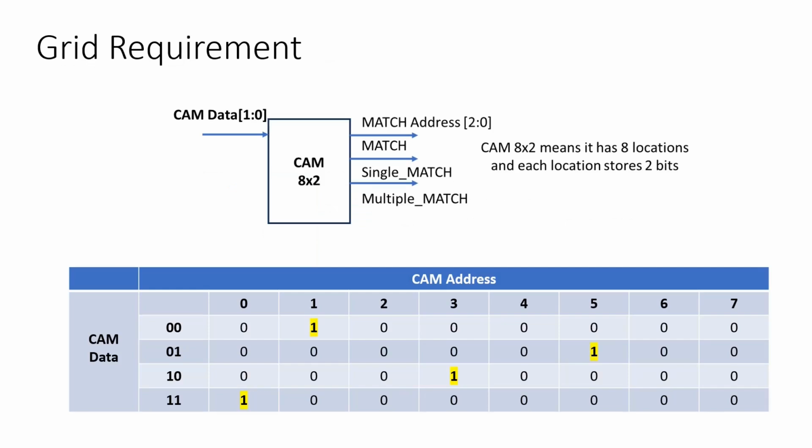Friends, there can be various ways to implement CAM memory, and whichever way I tell you is just one of them. The way I am going to tell you needs a RAM memory, or in FPGA terms a BRAM, that is block RAM. Now let us see how to implement a CAM memory using a RAM memory. The RAM memory behavior is well known to everyone in the digital community, so we are not going to discuss it here.